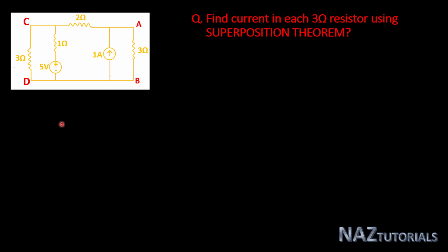So in the circuit solution, our key point is for the second circuit, that is for 1 ampere current source, to clear the concept of current divider rule in the multiple sections. For the 1 ampere current source, you can easily use the nodal analysis, which will give the solution for branch AB and CD.